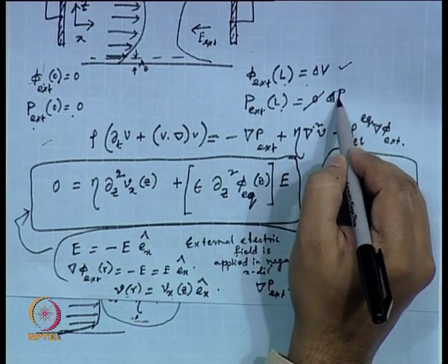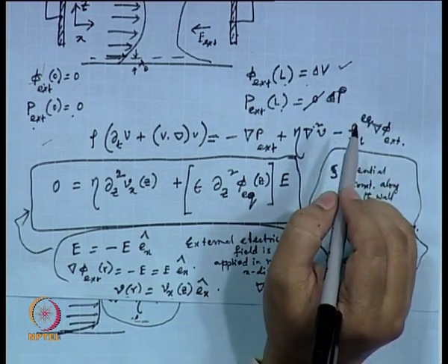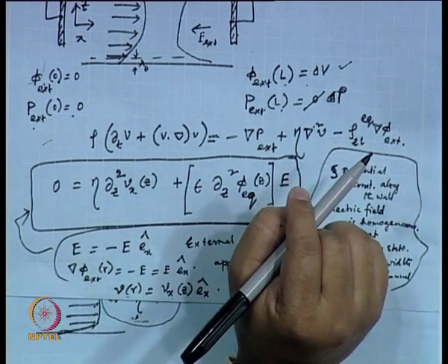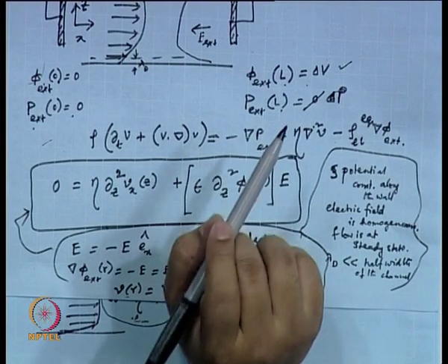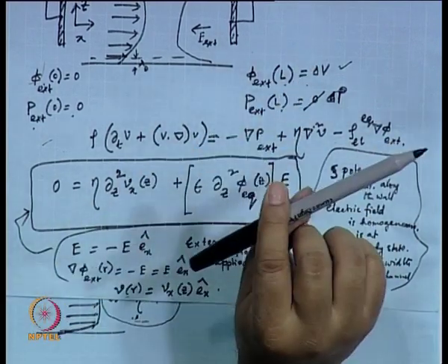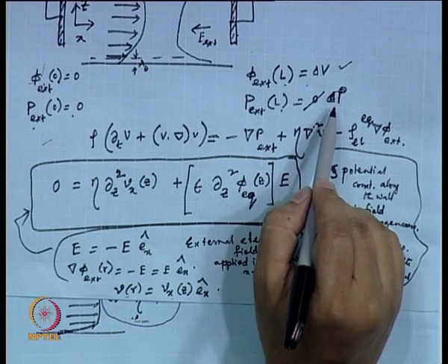That means, we will try to find out if it has to act as a pump, it has to act against a back pressure. You have to pump the fluid through a channel, through certain media like this. That media or channel will impose a back pressure, if the outlet of the channel is open to atmosphere. But to get the flow going through that media, you need to overcome some back pressure. So, instead of 0, we need to put this as delta p.